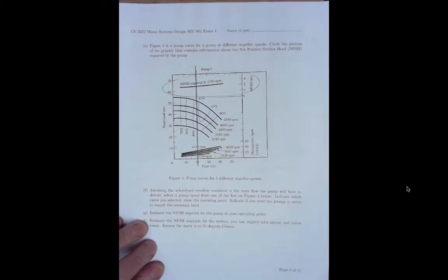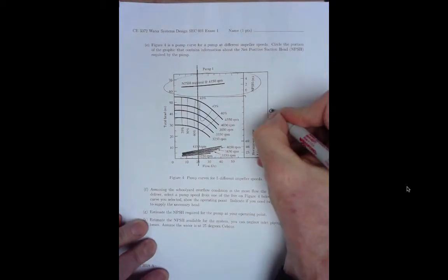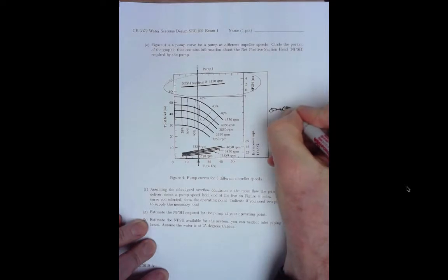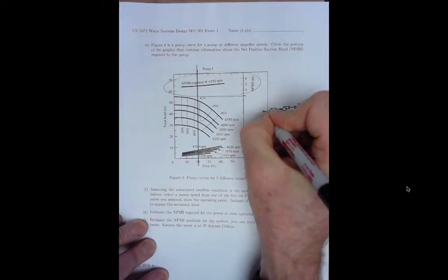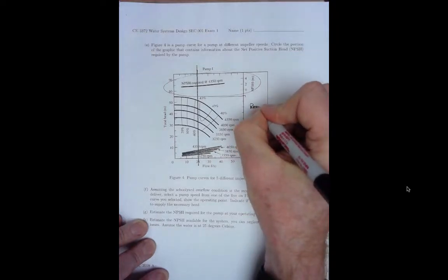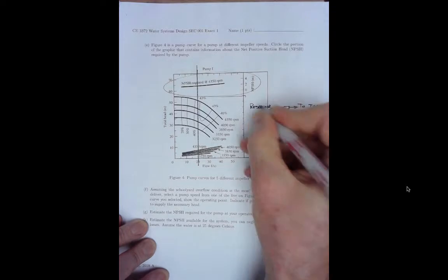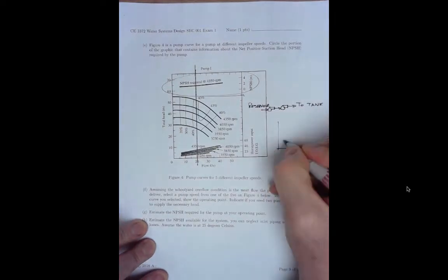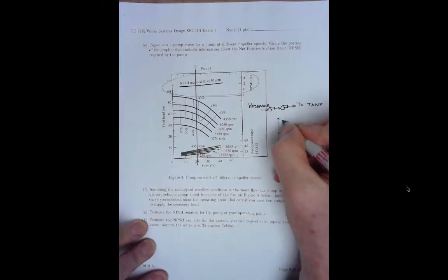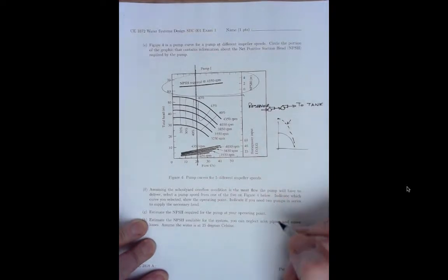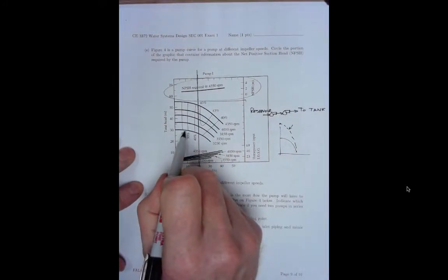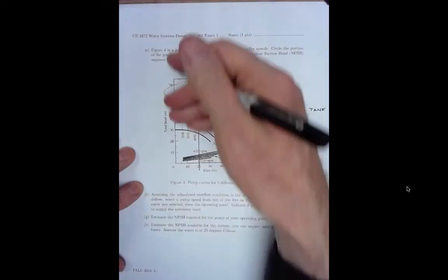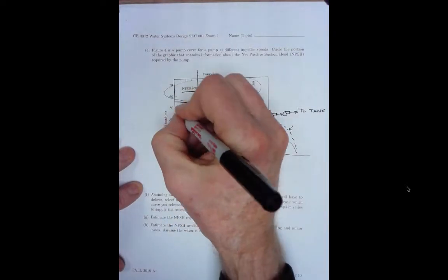None of these pump curves can supply that as a single pump. But if we run the pumps in series, then the heads will add. So it's as if we've taken that pump curve and then we double it, and we're going to operate on this squared line here, on this dashed line here. So two of these pumps in series, the effect it has on this drawing right here is simply to double these numbers.